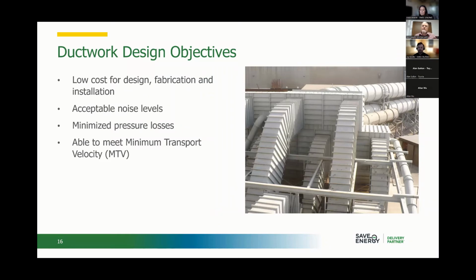And so now all of a sudden, if you try to make your ductwork too small, now you've got to silence it. And if you silence it, not only do you have the pressure loss of this ductwork, which is under designed for the flow, but you've got a delta P across your silencer that you've got to worry about. And so, some of these questions that involve fan selection, well, add that to the losses that you now have to be accommodating here.